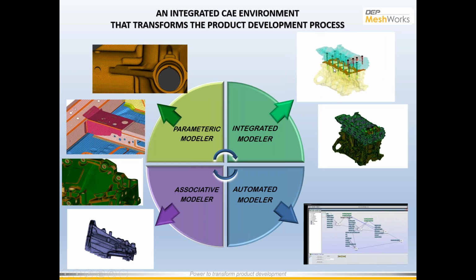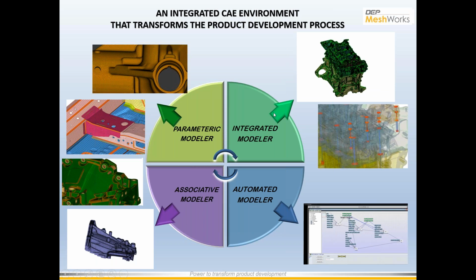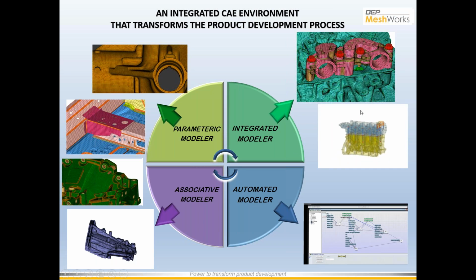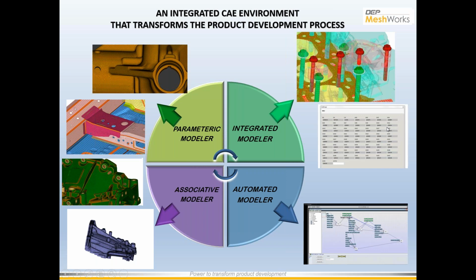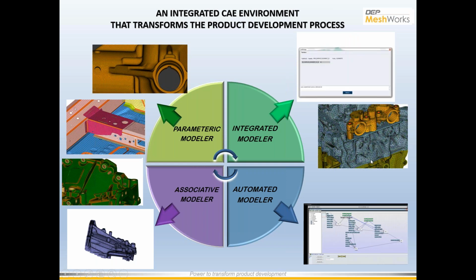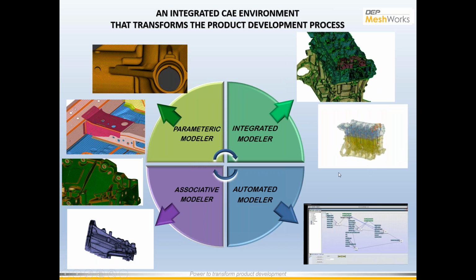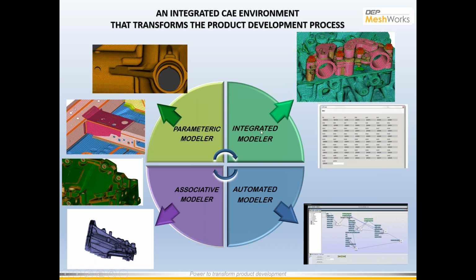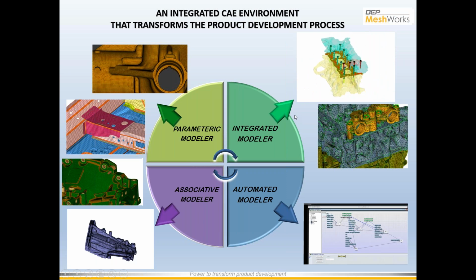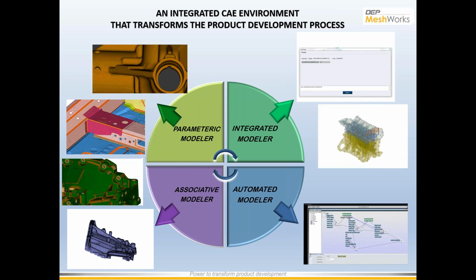and contact modeling. So as we all know, for durability and stress analysis and fatigue analysis, the devil is in the detail. So Meshworks can, from one database, simultaneously generate a durability model and at the same time a vibration model, for example, which tends to be in general much coarser, and the connection scheme could be different, and the entire modeling technique itself could be different. So you can templatize an attribute for durability, a template for noise and vibration, and from one database, you can generate multiple models. So this way, you can really reduce your model building time. There is no duplication of effort having to repeat both the kinds of modeling.